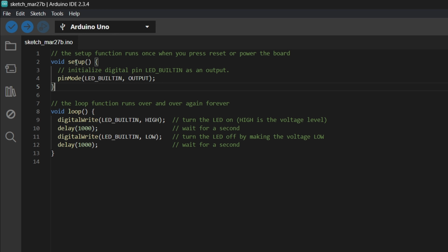And then you again invoke the digitalWrite function, and you write to the same pin, but you set it to LOW, and that will switch off the light. And again, you wait for another 1 second. And if you think about it, as soon as this completes, it runs again. So you can think of copy-pasting this code an infinite number of times just below this loop, and it will just set to high, wait, set to low, wait, set to high, wait, and so on and so forth.